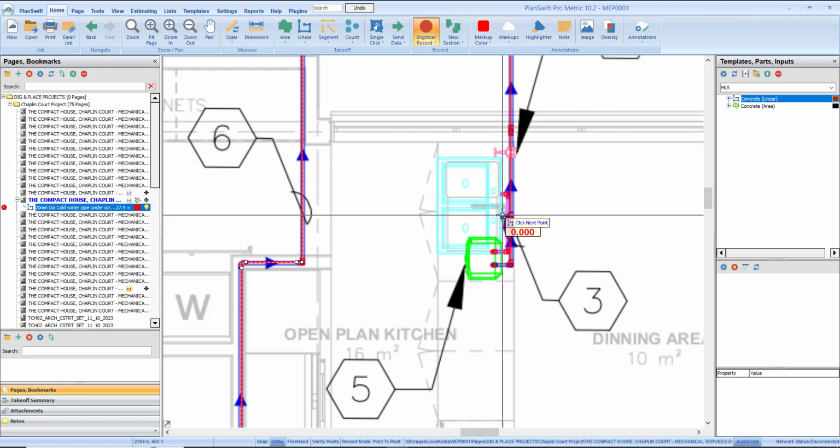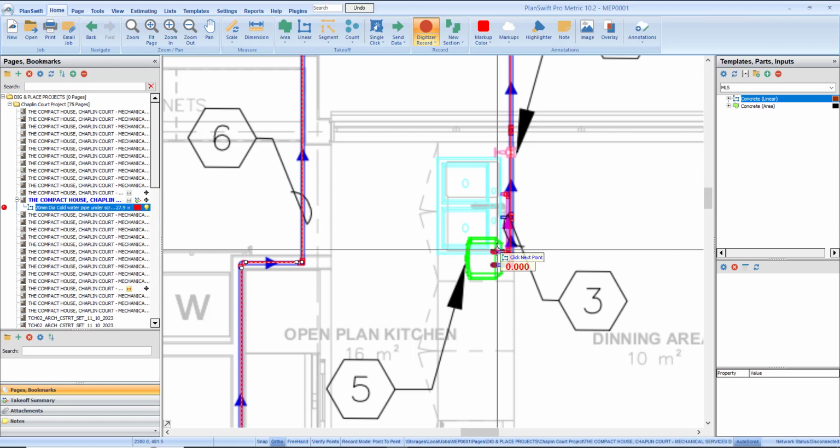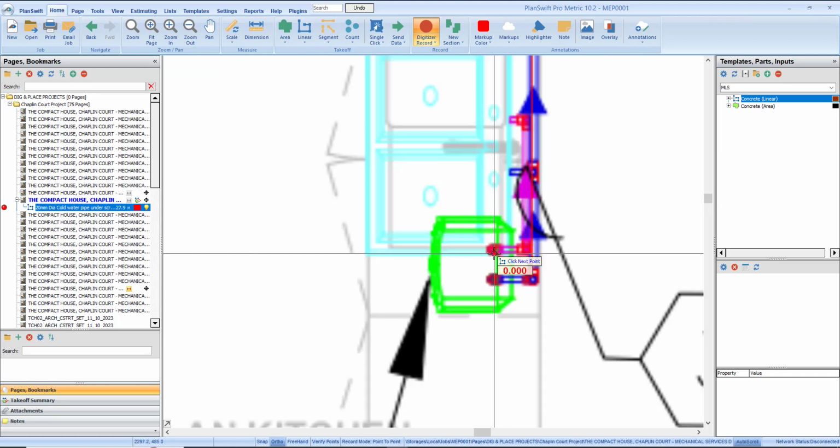Again, there is another pipe that we are kind of omitting, but since we are on it, let me also point that out. You see there are smaller pipes that are connected from that 20 mm pipe that is in the wall to the sanitary appliance.